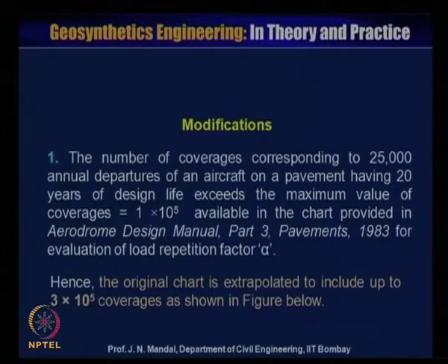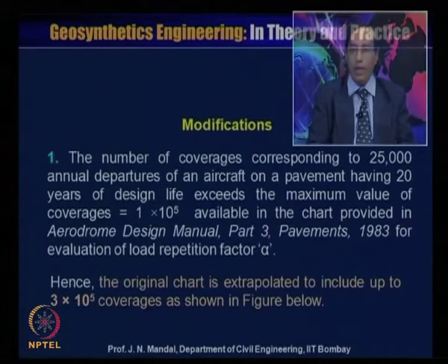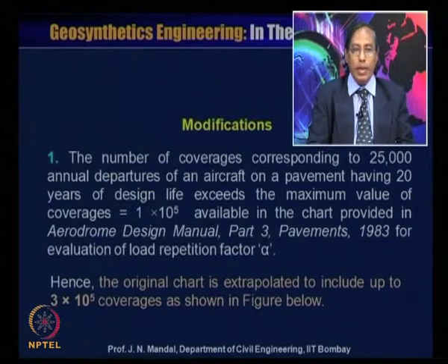The number of coverages corresponding to 25,000 annual departures of an aircraft on a pavement having 20 years of design life exceeds the maximum value of coverage, that is equal to 1 into 10 to the power 5, available in the chart provided in the Aerodrome Design Manual Part 3 Pavement 1983 for evaluation of load repetition factor alpha.